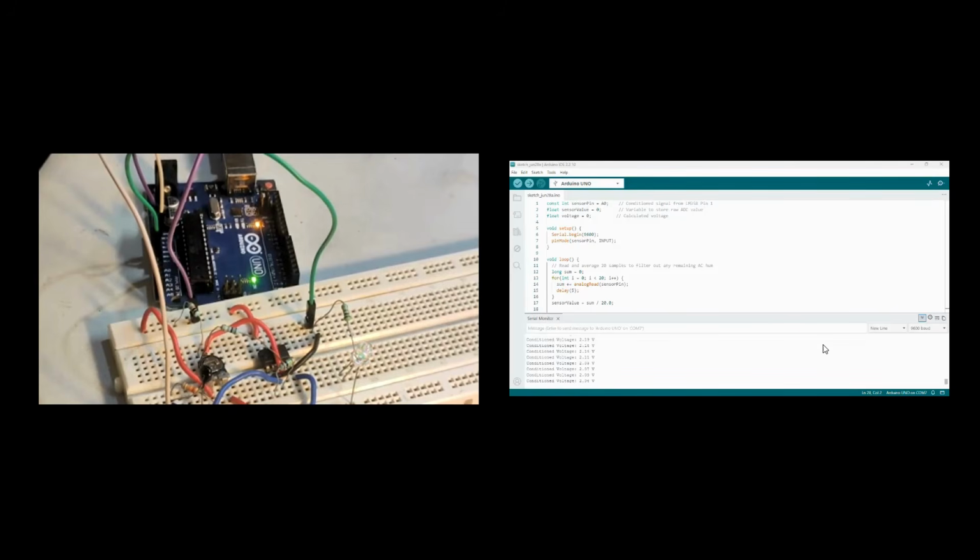So I have already shared the code for this. Very simple. A0 is connected to pin 1, 5 volt. As I told you, the sensor value starts at 0. Of course, here we have not started with 0, but we will start with 0 on the analog pin. The baud rate is 9600.